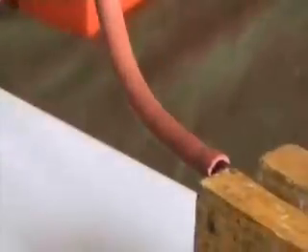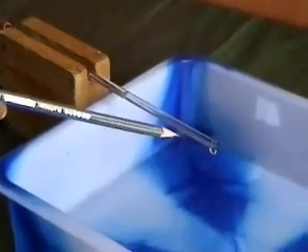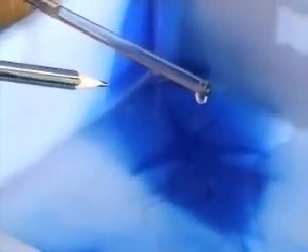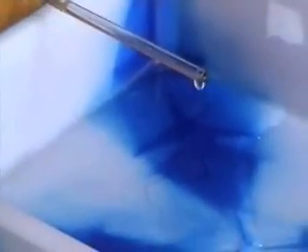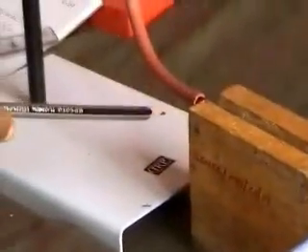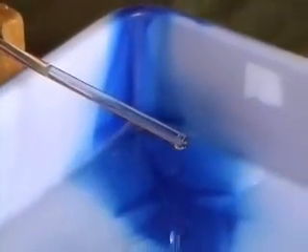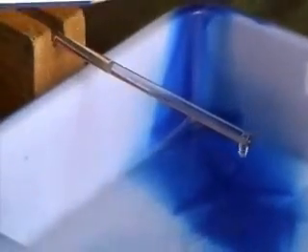So this is how you should adjust. You can see there should not be any constriction in the tube that goes to the capillary tube. It should be a free flow of water. Now you can see that when it starts coming, the height of the liquid starts reducing. The flow is more or less drop by drop. You should ensure this before you start. You should also ensure there is no leakage when the water is flowing in between. The tube should not leak. If there is something like this, first report it to the attender.